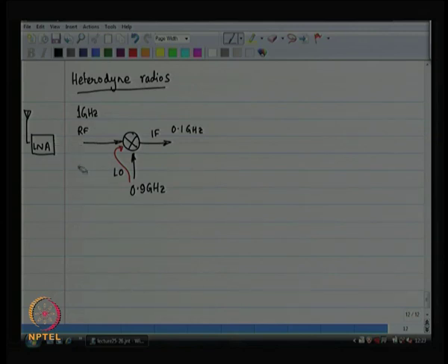So, what we put over here is something which is called an image reject filter. The job of the image reject filter is to keep your desired signal and to get rid of the blocker. Okay. If your local oscillator is at 0.9 gigahertz, if your signal is at 1 gigahertz, then the image reject filter should be a filter that cuts out 0.8 gigahertz, allows 1 gigahertz through. Something like this, all right.